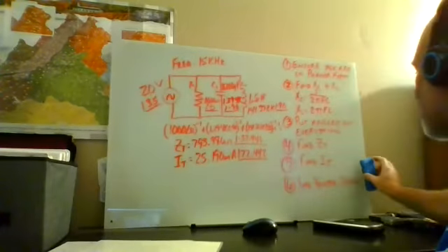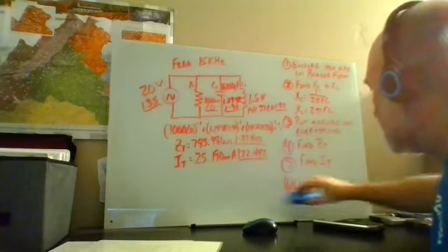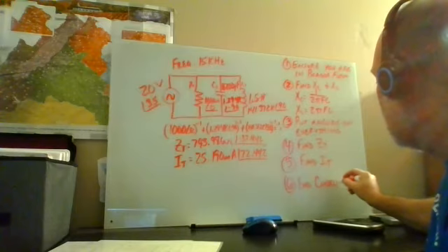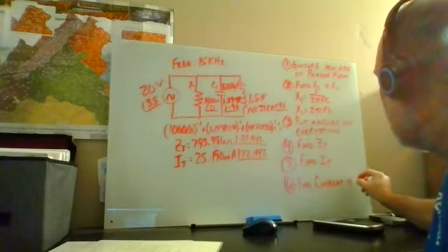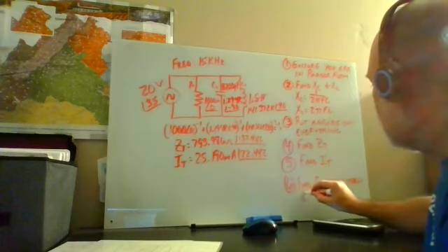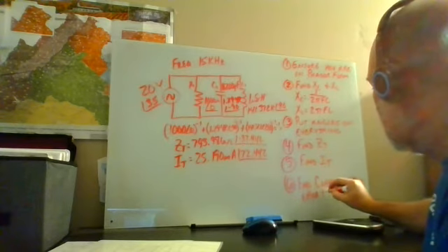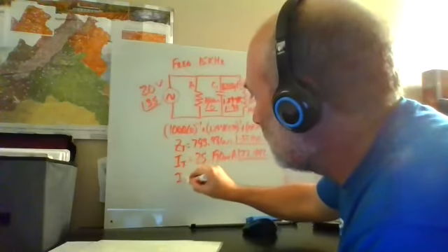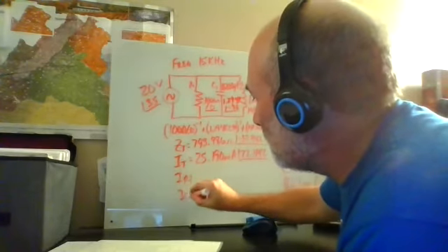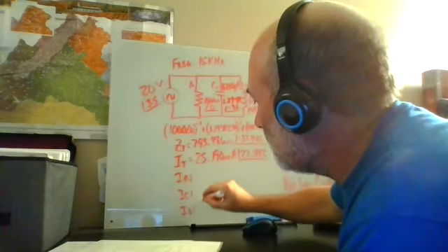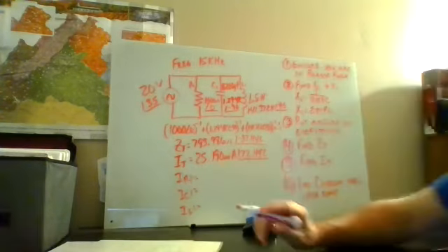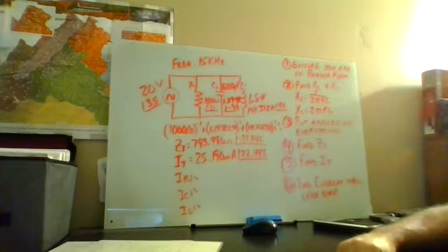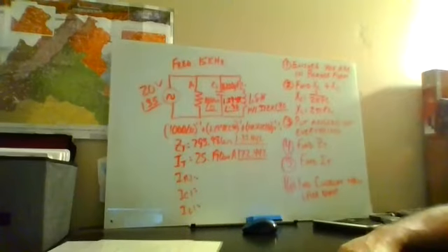Now, this is where my last step is going to change because I'm not going to find voltage drops now, right? I'm going to find current through each component. So I'm going to find IR1, IC1, and IL1. Because I know the voltage drop across each of them is going to be 20 volts at an angle 35 because it's a parallel circuit and my voltage stays constant.